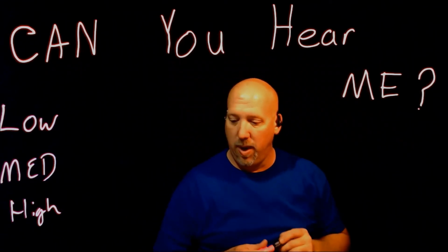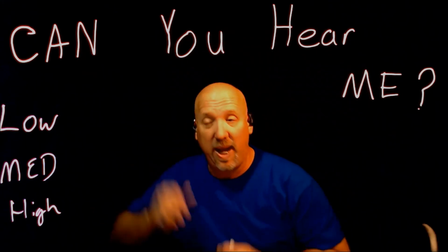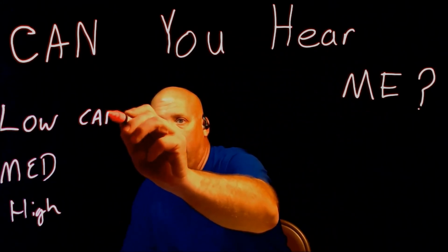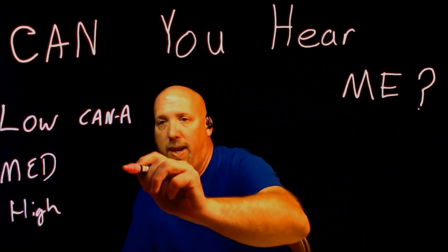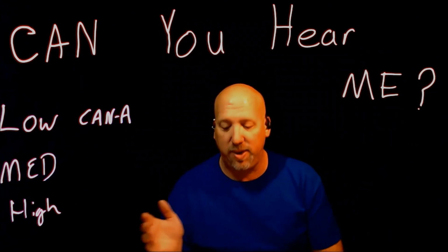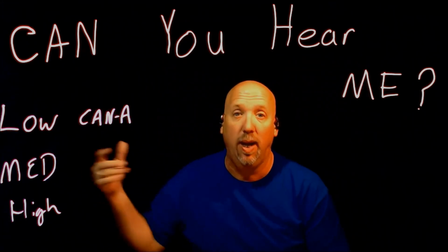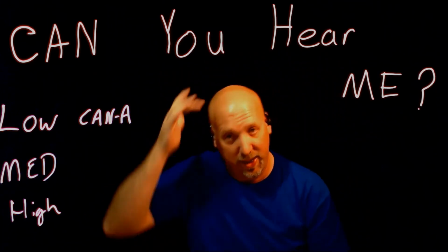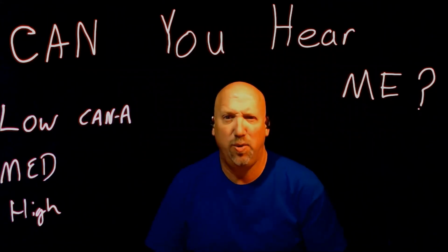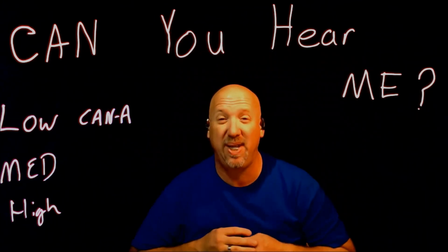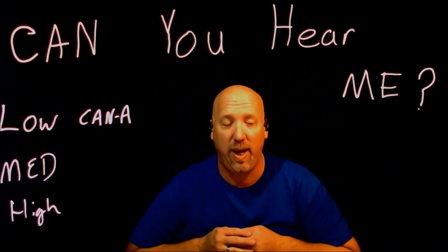All right, low speed, it's CAN A. This is the general category for low speed CAN communications. This is ISO standard 11519. You don't need the ISO standard really. You don't get quizzed on things like that. Data communication on CAN A is about 10 kilobits per second, kbps.